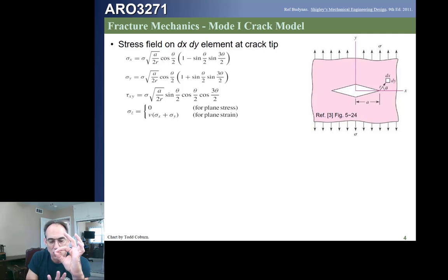The other thing you might think is, well, although it's a peak here, that means all the stress lines that came like this are kind of tightening right through there. That's why it's so high. But out here, they didn't have to change much, so the far-field stress still applied. But then as you move away, the loading is going to come back and work its way back through. If you move far enough away, the loading will be uniform again. So not only will the stress change as a function of the width or radius away from here, but it also changes as a function of this dimension here.